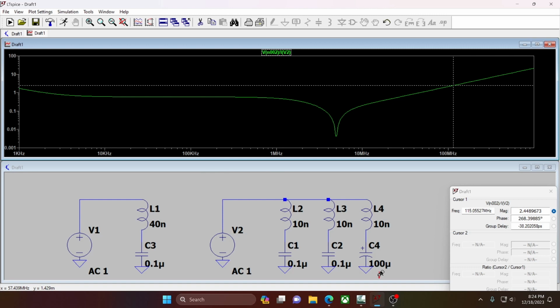We don't want some weirdo change to an IC like a rise time change, which is only getting faster, to screw up our designs. I can tell you, I've seen it firsthand. It is a pain to figure out because nobody's going to tell you, hey, our IC's got a faster rise time now. You might want to check that. No, you're just going to get the IC in. People are going to say it doesn't work. And you're going to have next to no idea.